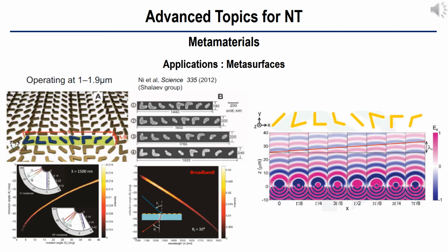Metasurfaces can arbitrarily control the following as a function of position: amplitude, polarization, phase, angles of phase, frequency, and reciprocity, such as nonlinearity, anisotropicity, and so on. As shown in the left figures, some arrays of metallic structures with designated symmetry and geometry can control the phase systematically.